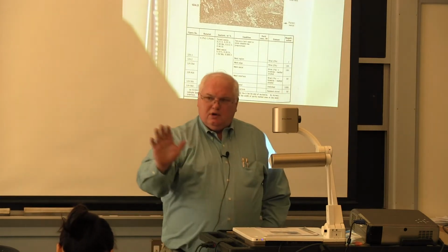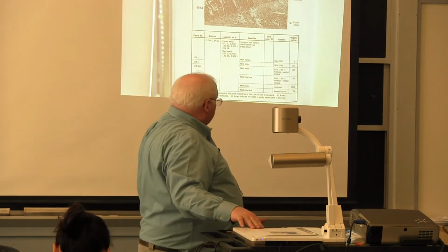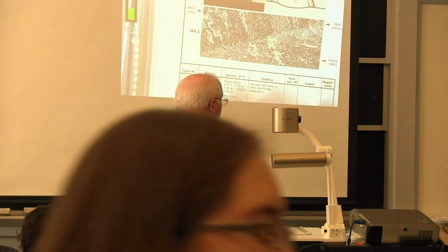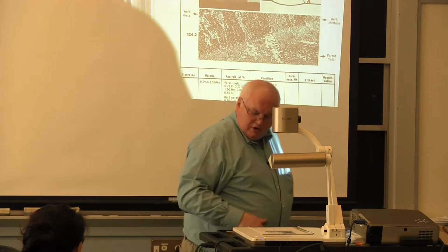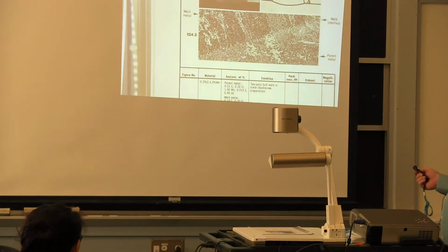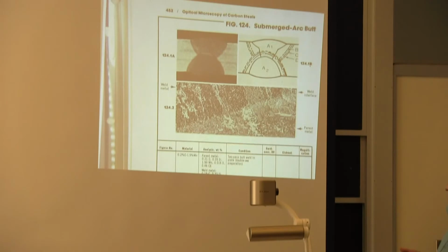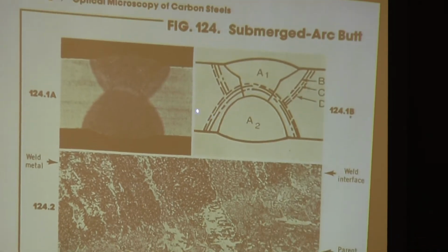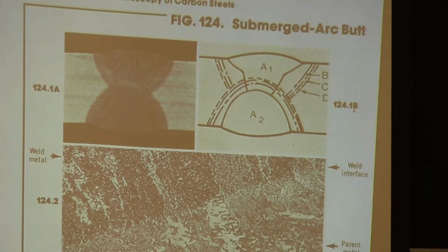It turns out the weld metal in steel, and the same thing occurs in titanium alloys, because you have hexagonal close packed at low temperatures, and at higher temperatures you have BCC. But you have the same type of thing. You have a crystal structure change, which allows you to have fine grain size in your weld. So titanium and steel, because of this allotropic crystal change, can give you weld metals that have as much strength as the base metal. If you pull a tensile test, you'll find it'll fail in the base metal, even though the weld metal is sort of an as-cast structure.